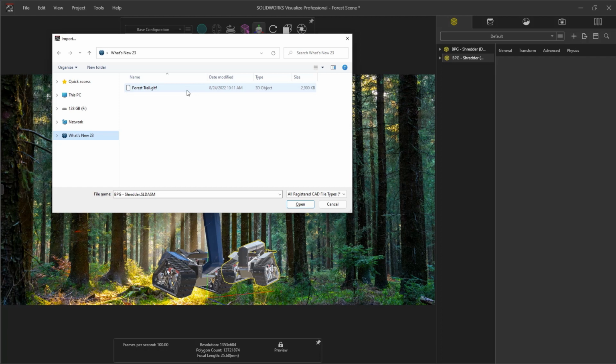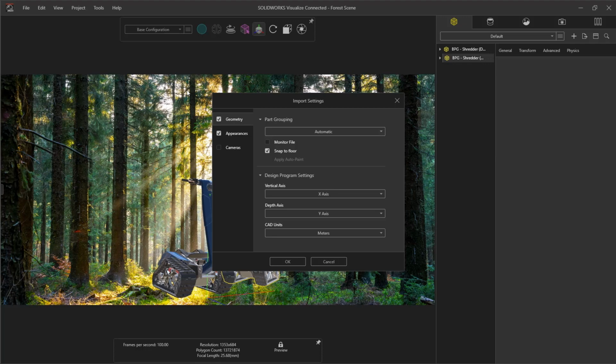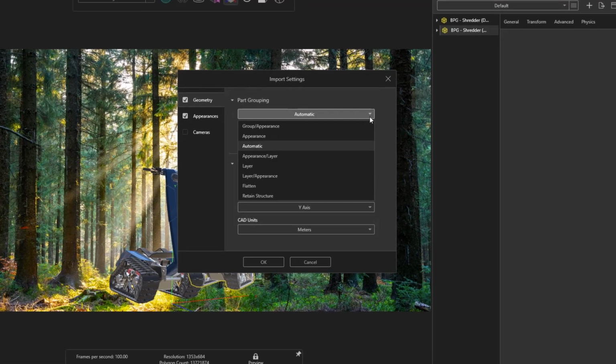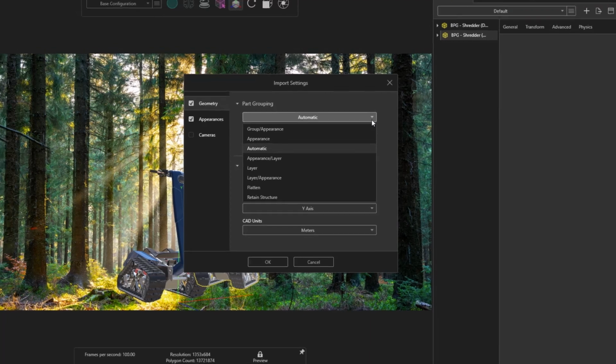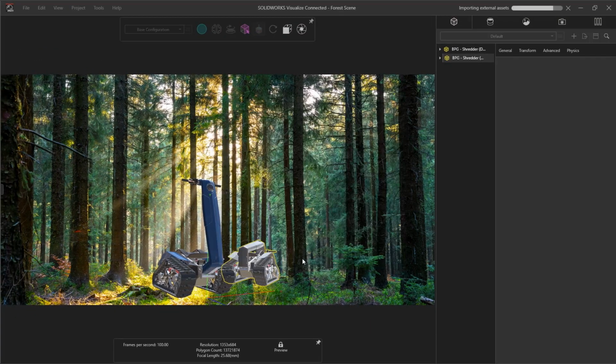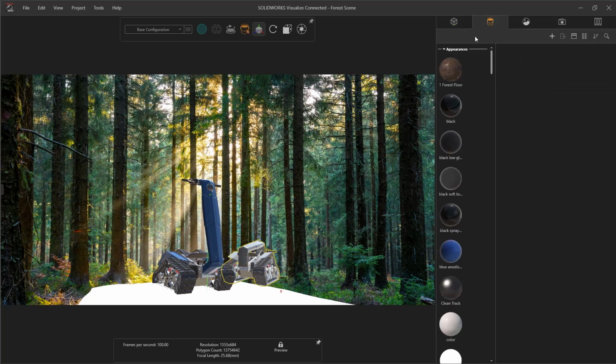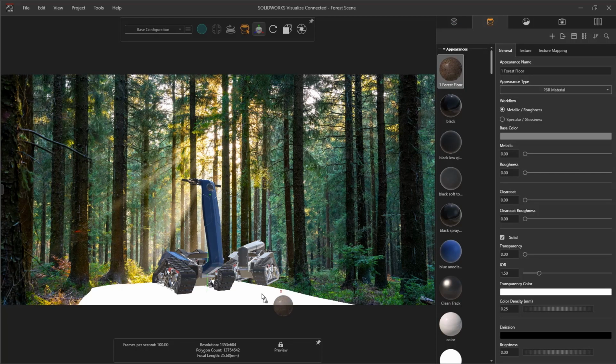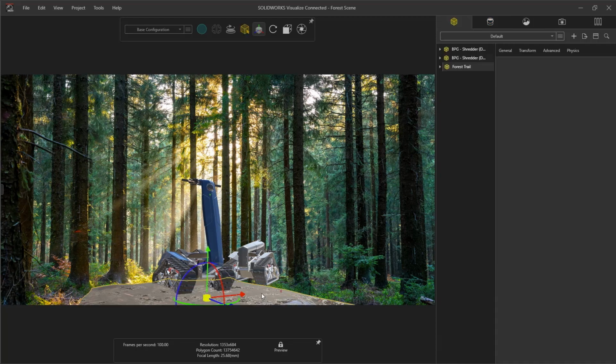Visualize has always been able to take advantage of nearly any type of geometry you can get your hands on. In 2023, we'll see that the standard import options are still available for any non-SOLIDWORKS file, such as this GLTF file. It is common practice to improve performance by making use of preview mode while setting our scene, especially if it involves complex or high detail models.